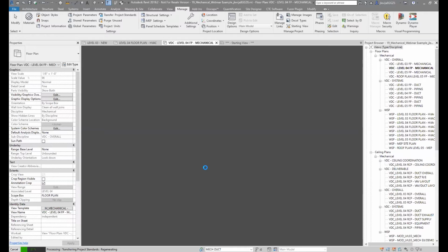Now, one thing that's beneficial with how the MEP productivity pack is set up, something specific to VAV boxes that I enjoy is we have VAV boxes in here. We have multiple types, and of those multiple types, the first thing that I like to get with them is having the option to swap my control side from my piping side, because depending on who the manufacturer of the VAV box is, there could be a premium to keep some of that cost on one side or the other. Okay.